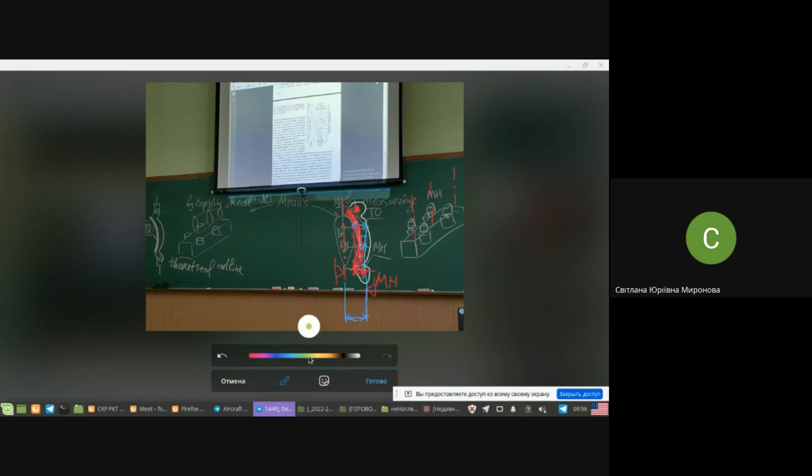Actually, despite being called the coordinate measuring technique, they really used templates anyway. Templates were carriers of those axes and contours, both axes and contours. Here is the template of the contour, the template of jig it's called. When it comes to the jig, we call it the template of jig, and the template of jig has a base hole. What is a base hole? A system of base holes. It imitates this axis, no? Like two points that you might draw a line through. That is the axis. And also it repeats the contour.